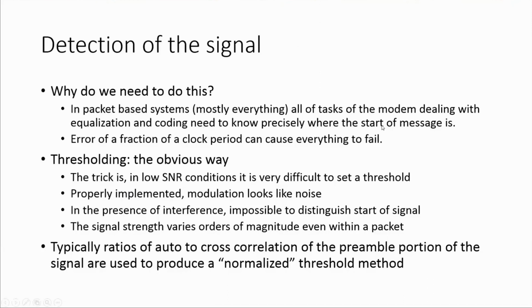If you're off by 1 bit, everything fails. If you're off by a fraction of a clock period, everything can fail. So if you don't synchronize, starting with where's the start of the thing, whether it's the preamble or the actual data packet or any portion of the correction, it'll fail. So that's crucially important to be able to detect the beginning.